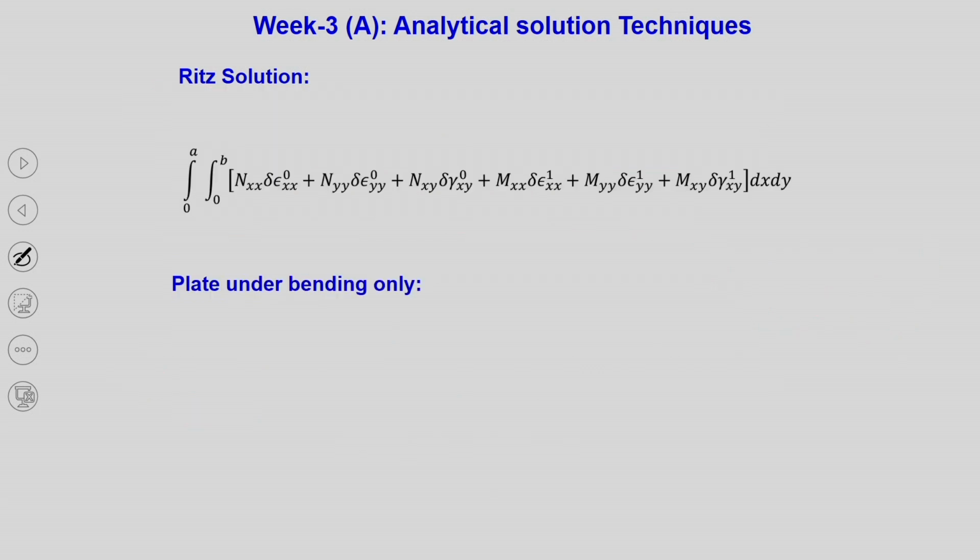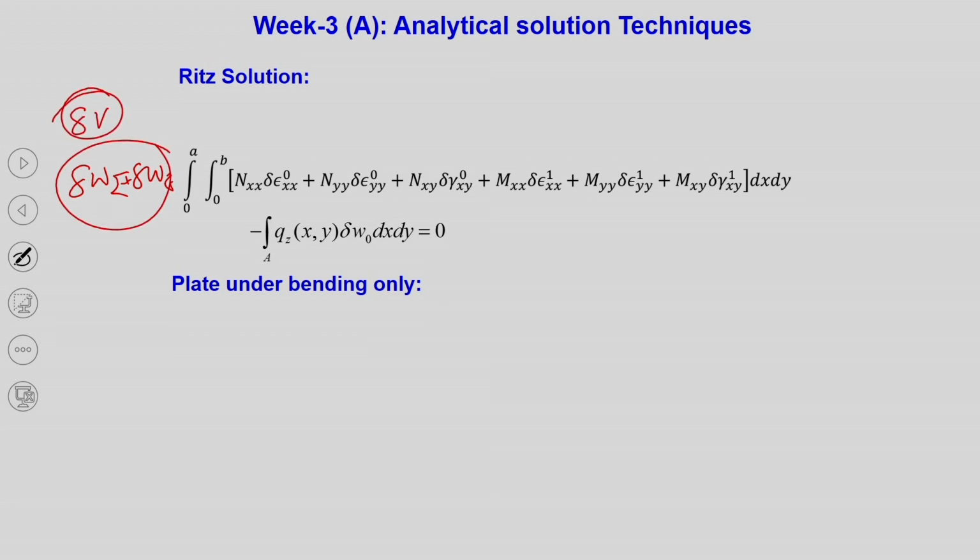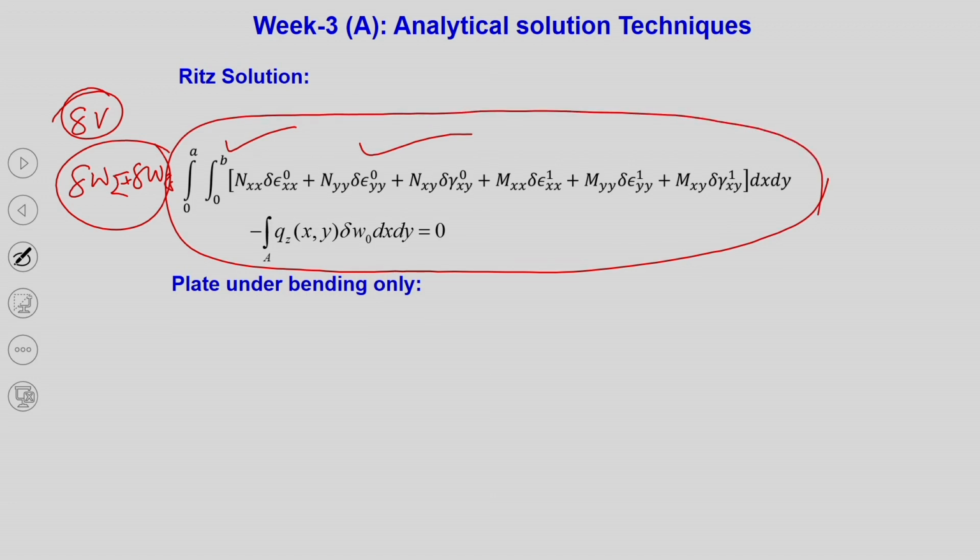You must know the weak form of the equation. Most of the time in the books you will find minimum potential energy and some other things, but recently we have developed del Wi, del We. What are these? Basically, the variation in the potential energy. So we can use this equation directly. No need for cramming what my weak form will be if I want to apply a Ritz solution, a Galerkin, or a finite element solution. Basically, in all these solutions we are going to use this form.